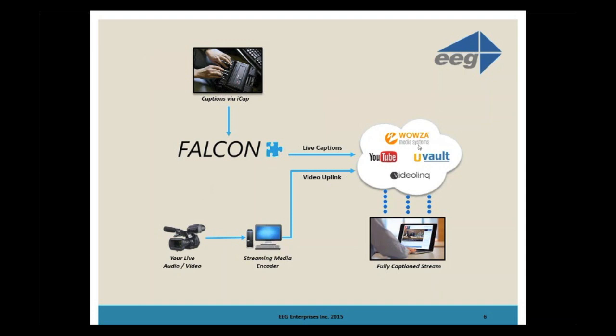The hardware encoder embeds the captions in the VANC space in SDI video, and then SDI video is fed into a streaming encoder, some of which can keep the captions and uplink them with the video. I think live stream, and they're not the only platform that has this kind of characteristic, is able to take captions, as far as I know, if they're embedded in the video, but I don't know of a way to get captions in there separately from the video.